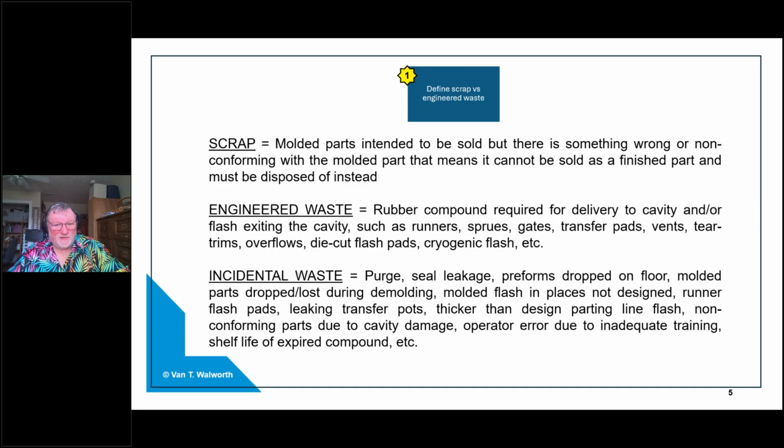So this is a case where, sometimes, if you have a multi-cavity mold, say 100 cavities, I find that if there's a damaged cavity, the molder might block off part of it with a tape or something like that to keep rubber from going in that spot if they're using a loader board for compression molds. Or if it's an injection mold or transfer mold, they might block up sprues to try to keep rubber from going in that cavity until they have at least 10%